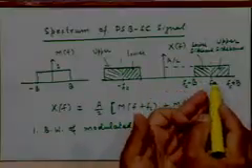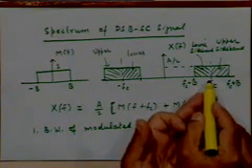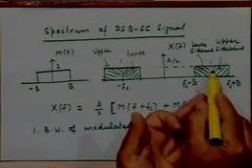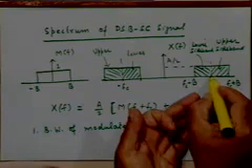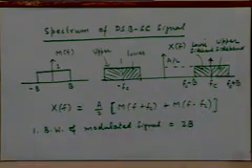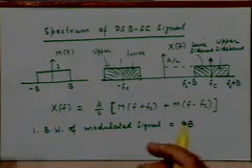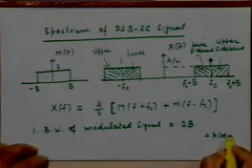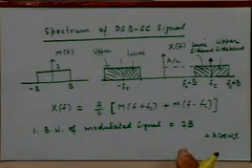Let's look at that. In this spectrum, does the carrier by itself show anywhere, other than the fact that the spectrum is shifted around the carrier frequency? There is no specific carrier component present as such. By that I mean there is no impulsive component at the carrier frequency. There is no component like cosine omega ct being transmitted, which is a nice thing because that doesn't really convey any information. So there is no impulse component at Fc, and because of that we call it suppressed carrier. That is, it doesn't have a carrier component located at Fc.